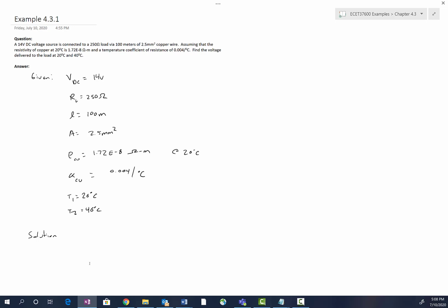First thing we're going to do is start by creating a circuit diagram. We want to see what this circuit looks like. What's the topology? What are the known values, etc. So this is a single phase DC circuit. There's a wire that connects the source to the load. So that's our line, and how much resistance the wire has. Here's the load. And then in single phase DC circuits, we have to have a return that current flows through. So that wire also has a resistance associated with it. So here's our circuit model for a single phase DC.